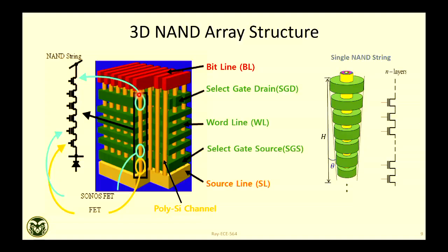But in the memory industry, you need very high yield, 80, 90%. Yield means you are on a process, you are making 100 chips, 100 die. Out of 100 die, at least 90 die should be functional. You should be able to sell them. But because of the structure, 50% of dies we used to reject because of shorts and a lot of process non-uniformity. But industry has solved all these issues.